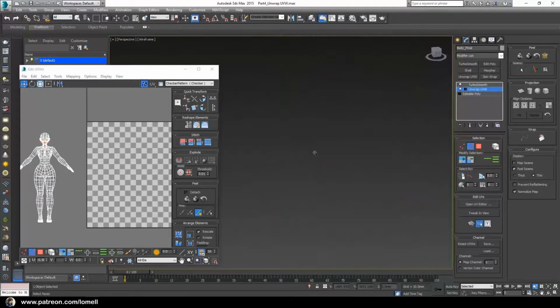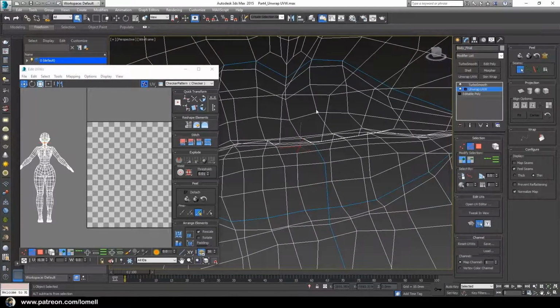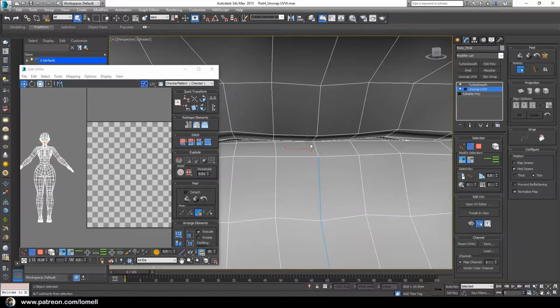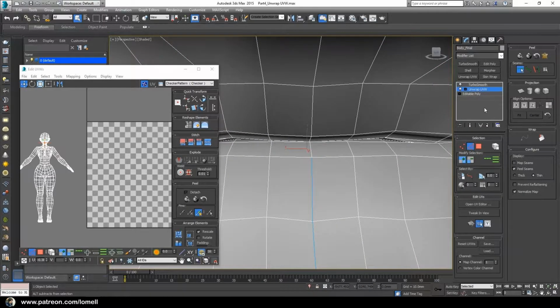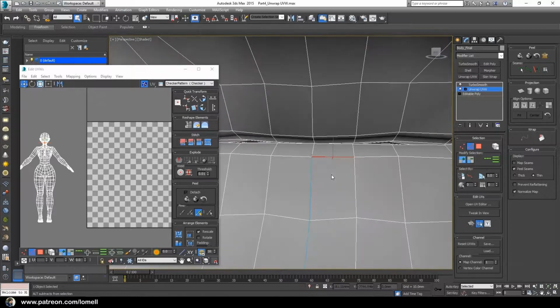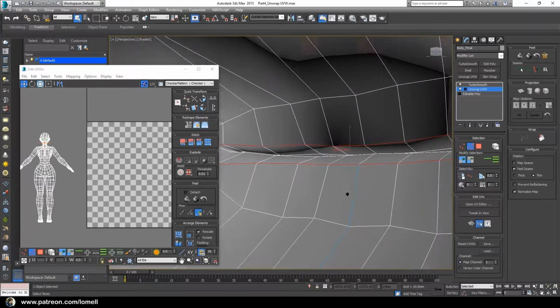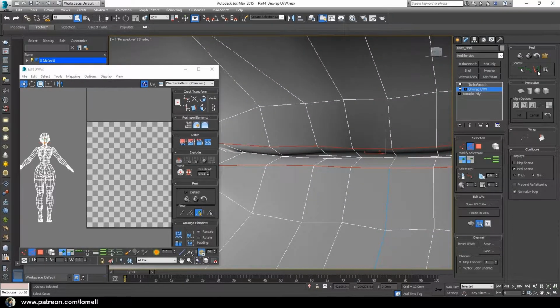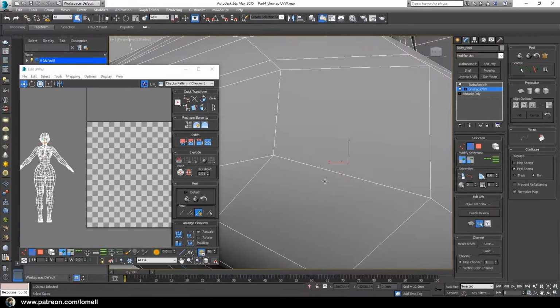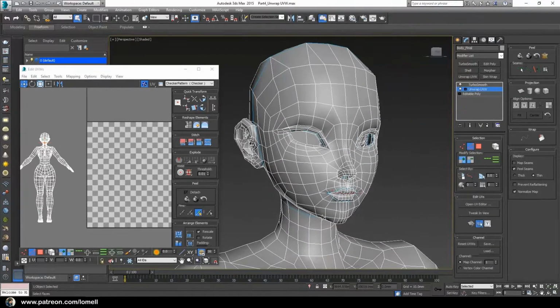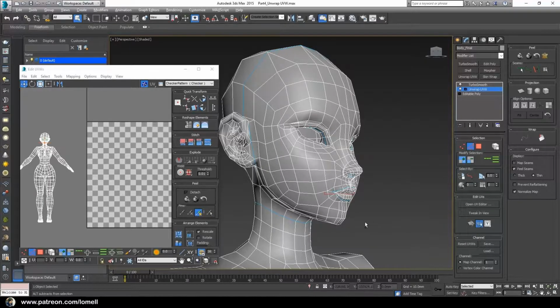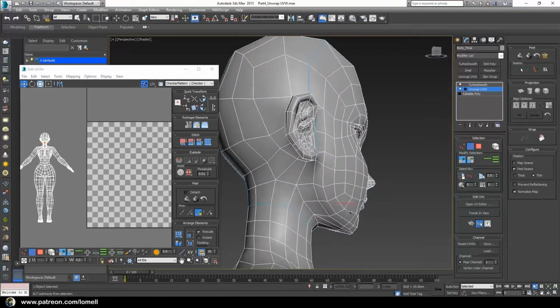So I think we should delete some of the seams. So press Alt on your keyboard and select this one and press F3, and then instead of extending those seams out of the mouth, we should select this one instead and loop. Okay, so that we can select the loop automatically and convert it to seams. Okay, so I think we are now ready to unwrap the first part of our surface.